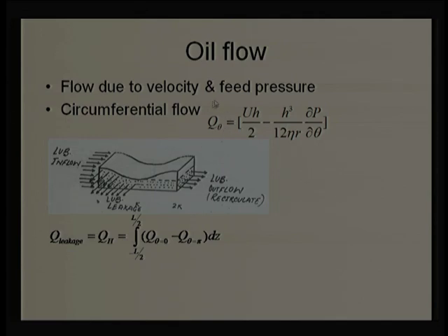And this overall leakage: the flow is coming in at maybe theta equal to 0, and at theta equal to pi the film thickness is minimum. Not most of the liquid, but some portion of the liquid is leaked out and the remaining portion is recirculated. We require this leakage rate because it gives us a cooling effect, because this liquid will be cooled again and come back, or can be returned using a pump arrangement. That Q leakage, as it happens because of the hydrodynamic action, can be given in another form also.